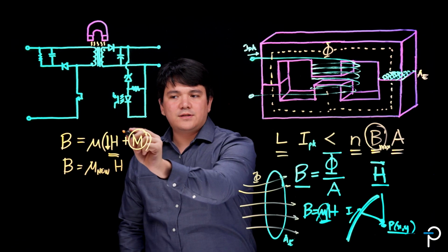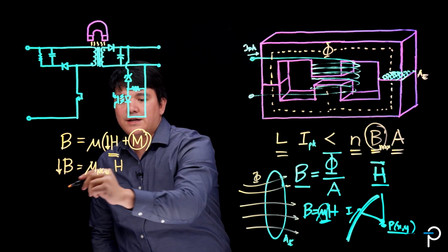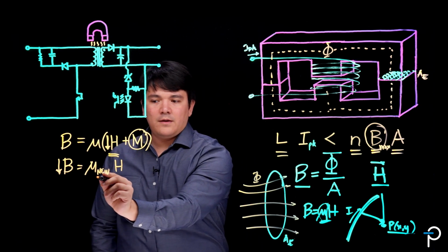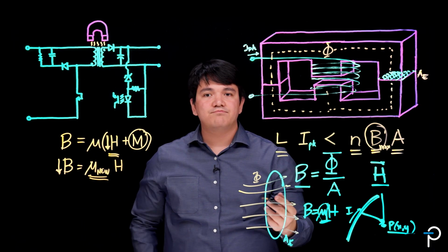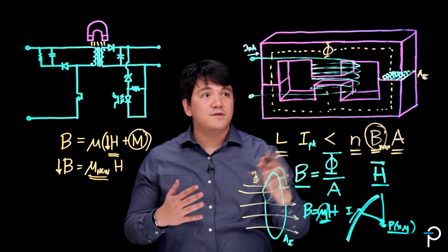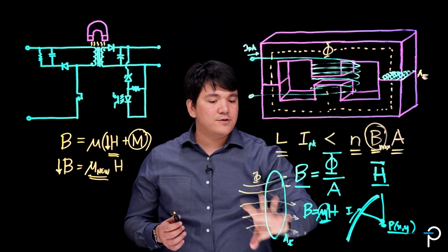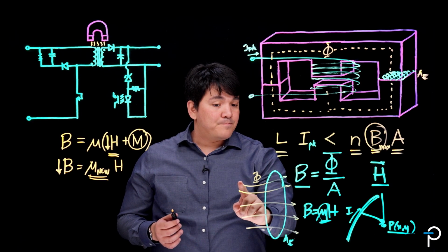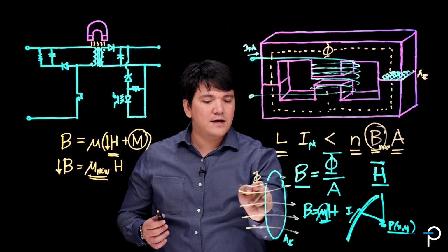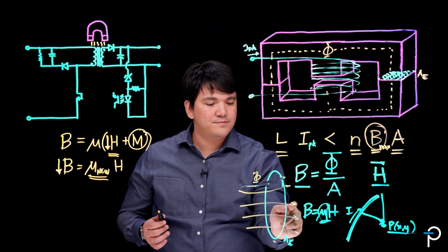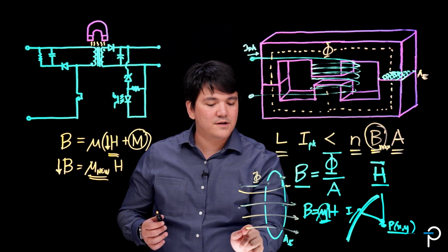And with a decrease in the magnetic field, a decrease in the magnetic flux density, you can also say that the permeability has changed. The material allows less flux going through the core. So if we look back on this example, your magnetic flux lines will actually decrease as a result of the magnet. So you'd be working with less flux lines.